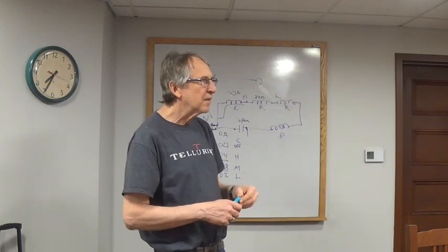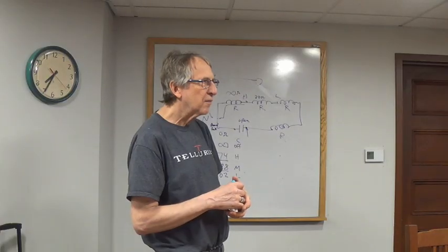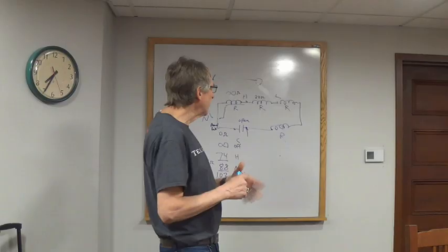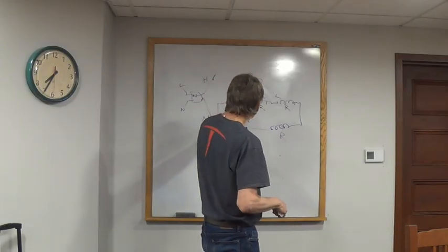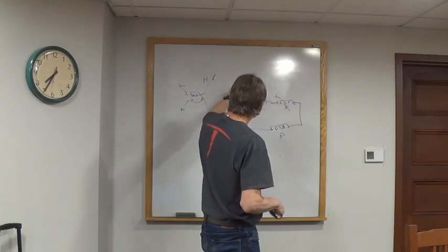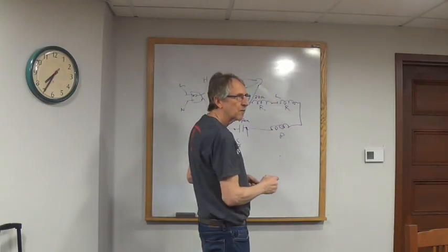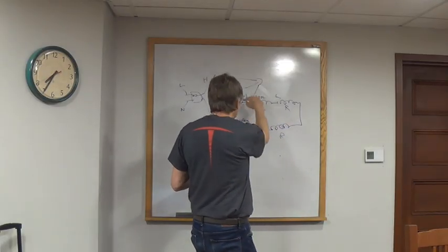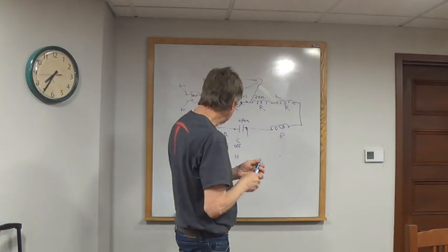Just gonna ask, so this testing that you're teaching us, this would only work with multi-speed? If it was just an on-off? No, well, with on-off, you're only gonna have these two guys, and so you're gonna have either off or on. So the same test would show infinite, and then it'll show you some resistance. Right.